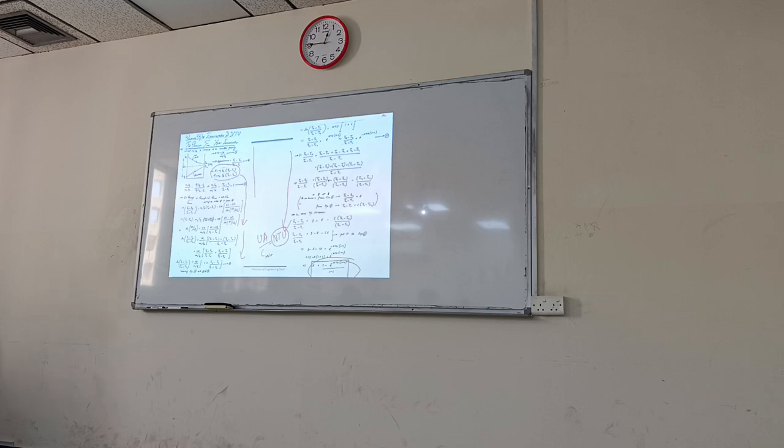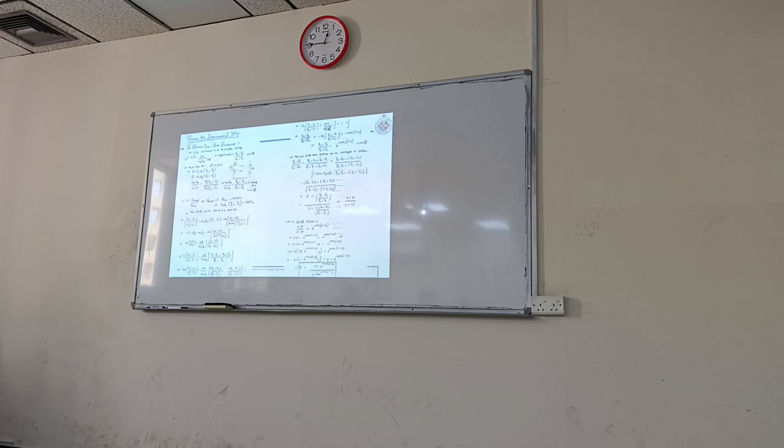So this is for parallel flow. Similarly, we have it for counter flow, and so on. Shell and tube, cross flow, they have developed. In every case, you will see this effectiveness as a function of C minimum over C maximum and this NTU, UA over C minimum. They have developed these correlations for many different types of heat exchangers in this form.